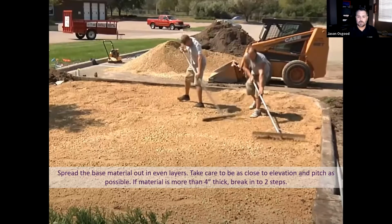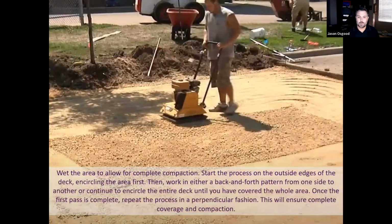So you're going to get some different compactions, but also keep in mind, you don't want to go more than 4 inches thick. If you have to go more than 4 inches thick, just break it up into 2 steps. If you've got to go more than that, break it up into 3 steps. But you're going to want to screen the material out, get it out as best as you can. Take care to stay as close as you can to your elevation and your pitch. And then once you do that, you're going to run a plate compactor over it.